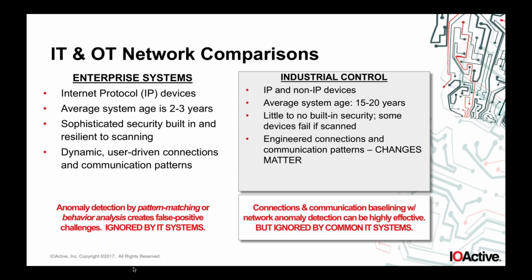In the industrial control space, in the ICS systems and SCADA systems, unfortunately, we have to drive these things for a great number of years, often on the scale of 2 decades or more. And because that is the case, with vulnerabilities like MS08-067 for Conficker and Stuxnet, all the way out to MS17-010 for the latest round of ransomware outbreaks, we have to have some level of strategy built into the network itself if we're going to get to the point of having any level of resiliency to these systems.